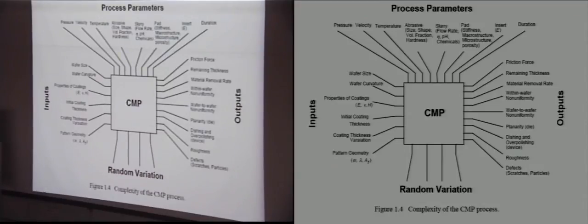If the number of particles is higher, then of course the passive oxide removal rate goes up. The slurry needs to be refreshed such that the pH doesn't change so dramatically, and of course your pad will eventually wear off. So you need to maintain that properly, and of course how long you etch it. So these are all factors that need to be considered, and therefore of course you have random variation also.